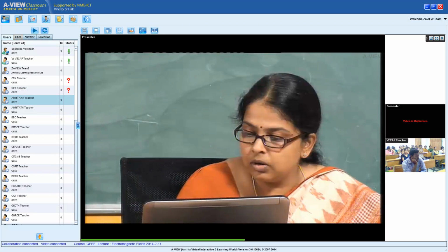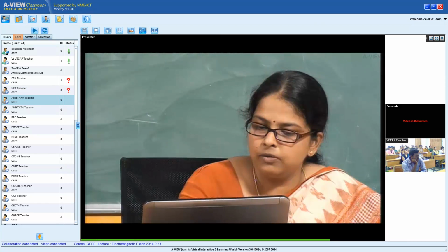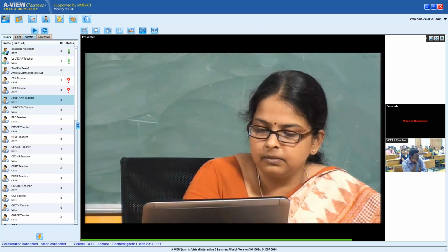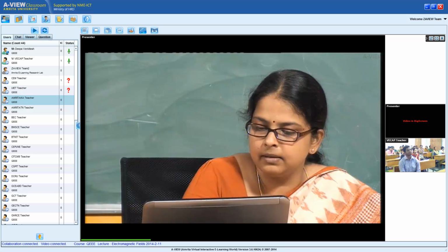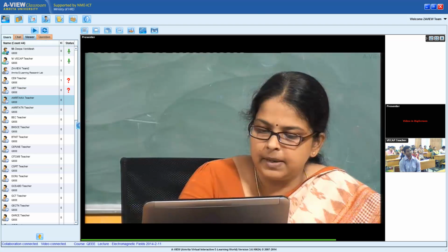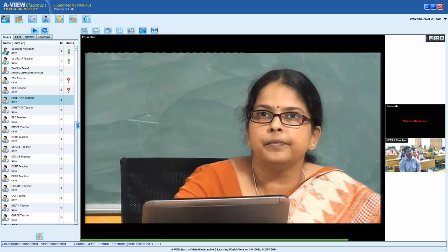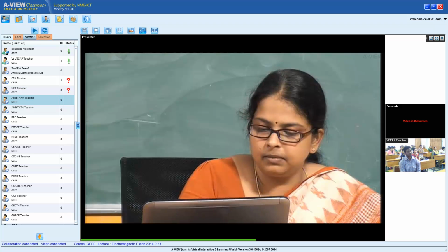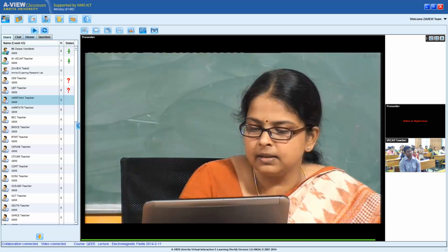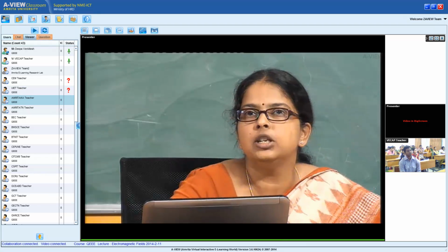So when I say 1 over R, it is not 1 over this R. It is 1 over RC, the resistance of the capacitance. For an ideal capacitor, RC is infinite, which means G equals 0. For an ideal inductor, the series resistance of the inductance is 0. So for a lossless line, you have R equal to 0 and G equal to 0.